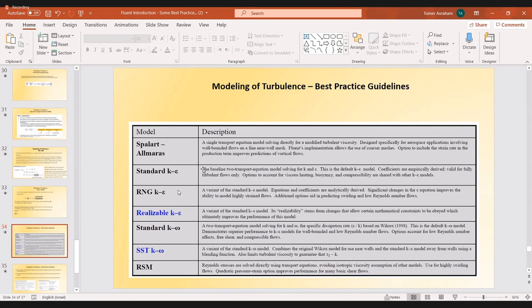The standard K epsilon is a model for high Reynolds. It's a high Reynolds model. Of course, we talked about the fact that all the K epsilon models are wall sensitive. The standard K omega is not used except for cases where there is no free stream. The boundary layer connects between the 2 sides. And then there's the BSL, which is not written here, but it exists. It could be used. Sometimes it's even better than the SST.